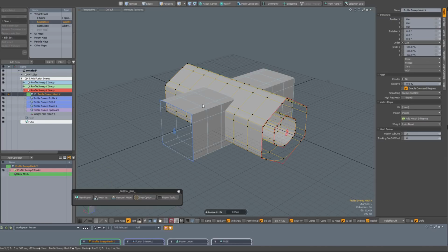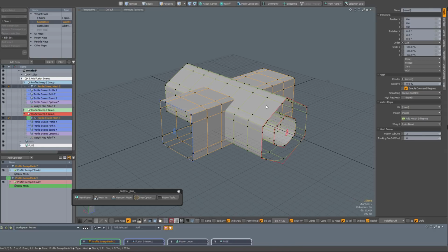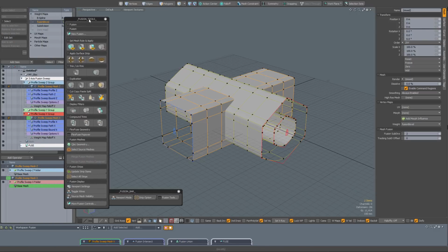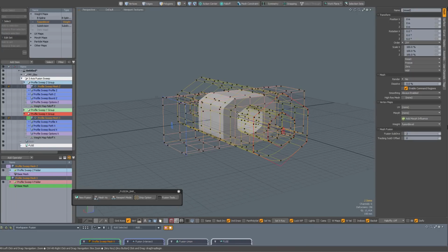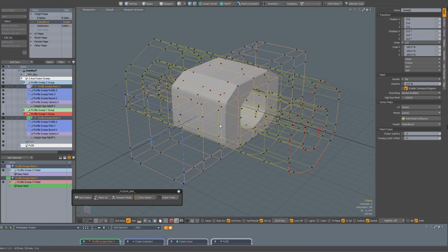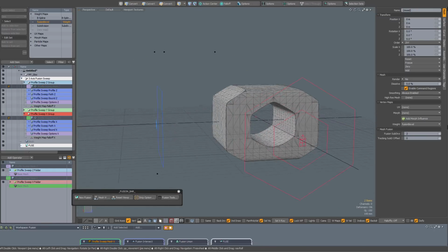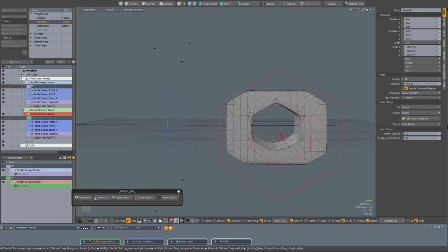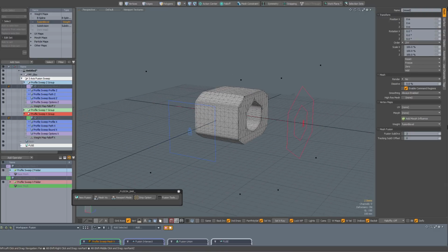And now select that Z and press the F key in the item list, that profile sweep mesh Z, and then together with my primary, and say in my fusion tools do an intersection like that, now you see that I have created a mesh fusion with those sweeps. So I'm going to toggle my wires just like that, press Ctrl F to toggle source visibility, and now you see that polygon that has been flipped because the normal is pointing the other way. It's making a hole just like that.